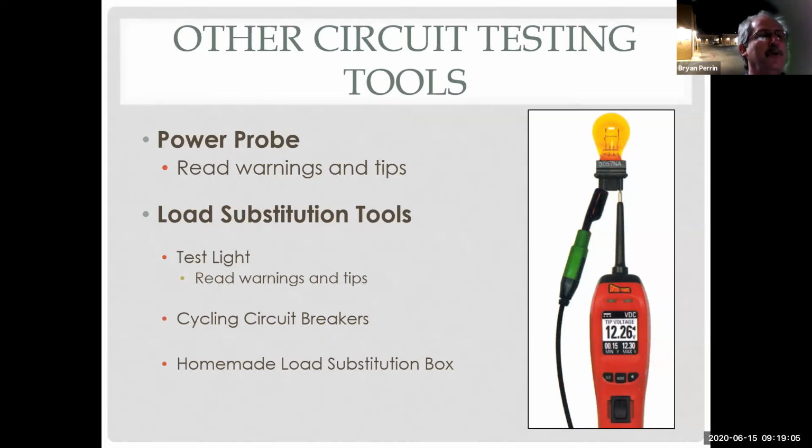So this is a power probe. This is the newest one. The 4 is the picture here. What's kind of cool about it is it has a wire that hangs off the side, which is ground. So I can actually put ground here and put power here and light the light bulb up to test it. Well, if I can light a light bulb up, I could probably use it on a window motor or a seat motor or anything else. And it has a circuit breaker in here for 10 amps.